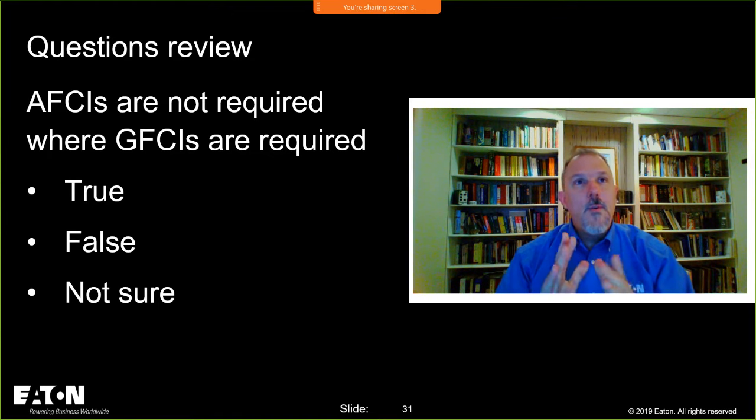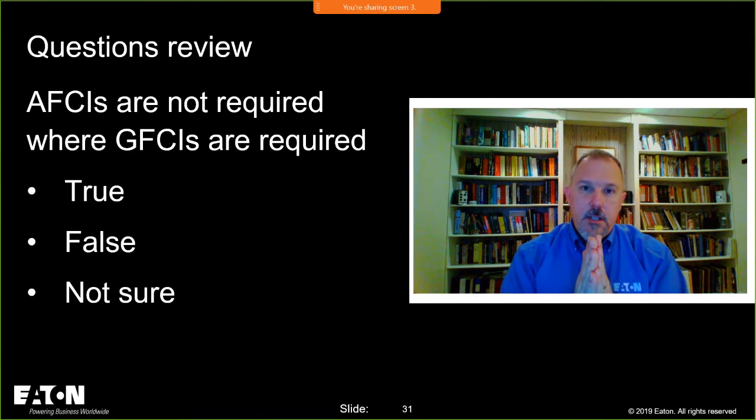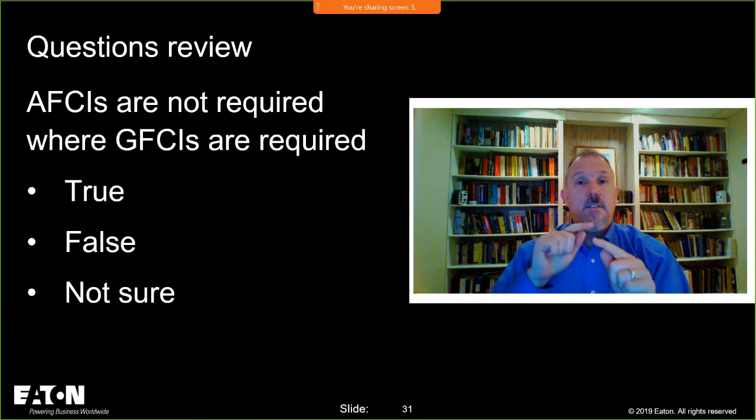If you say, I only want one receptacle for the refrigerator, I don't want anybody to accidentally plug anything else in on that dedicated circuit, then you could put a blank face GFCI, which doesn't have outlets where you can plug anything in. You just have a push to test button on the front, and you could land that in a readily accessible location.